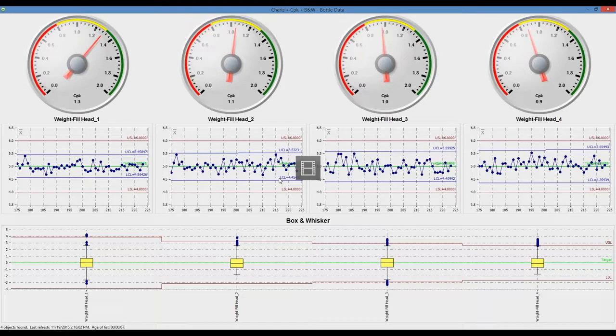And if you've explored data sets in WinSPC, there's many different templates there, many different ways to crunch data and find events. This is a handy way to have the system search to determine what variables it's supposed to show in the dashboard. The search in the data set could find variables with significant stat changes, or maybe those that have cost factors increasing using our cost analysis tools and calculations. Here's an example that shows a profile of multiple variables where their CPK has dropped to a certain level this month.